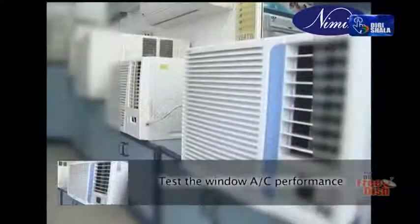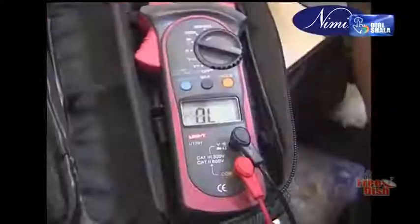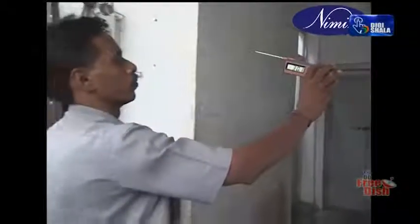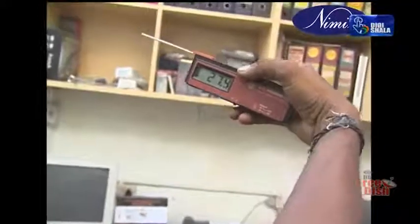Test the window AC performance. Run the fan and observe any abnormal sound or rubbing noise. Check the incoming voltage. Start the compressor. Check the ambient temperature and room temperature.